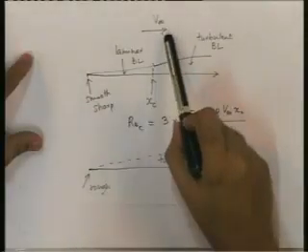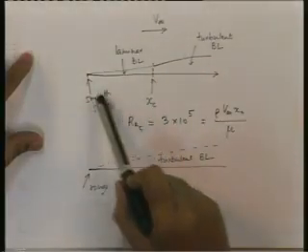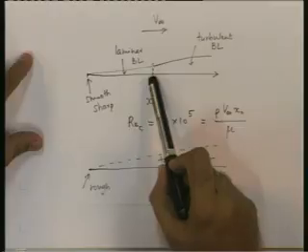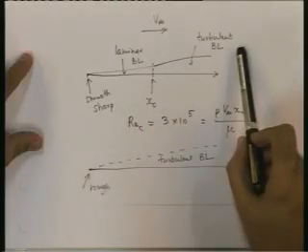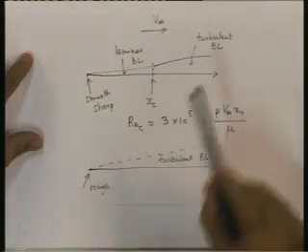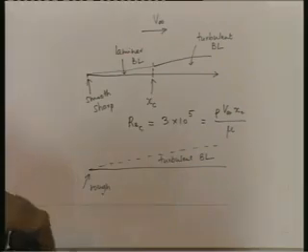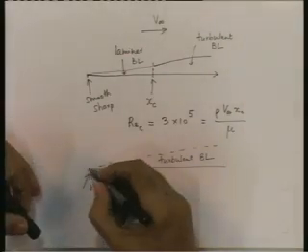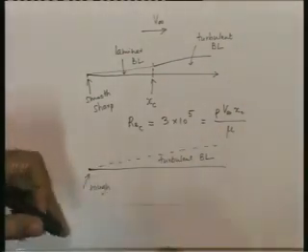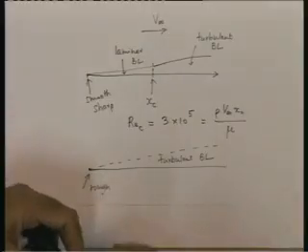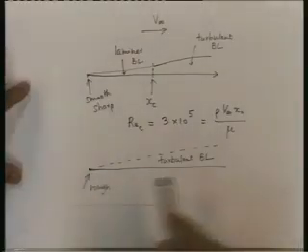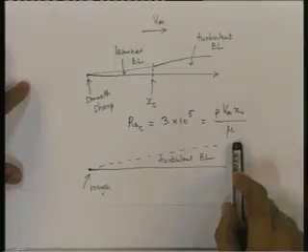In a boundary layer situation, under the same condition of a fixed V infinity, it is possible to have a laminar boundary layer first, followed by a turbulent boundary layer. Not only that, by appropriately roughening the leading edge or putting a small extension there, a small spur or a burr, you can make the boundary layer turbulent right from the leading edge.